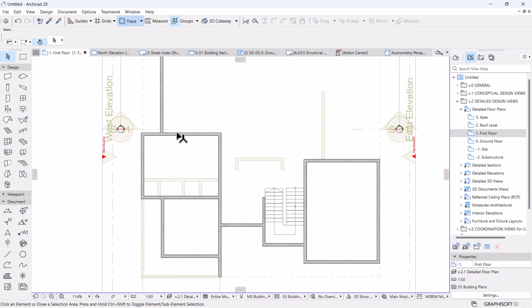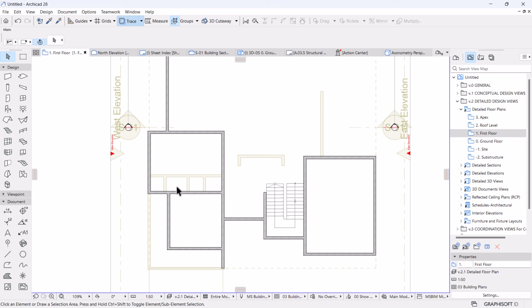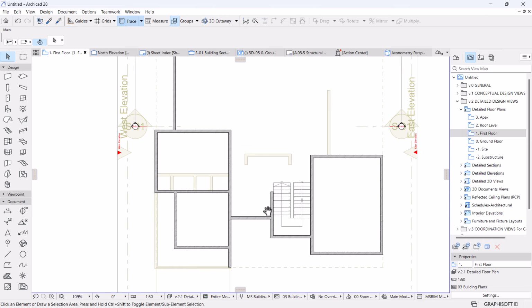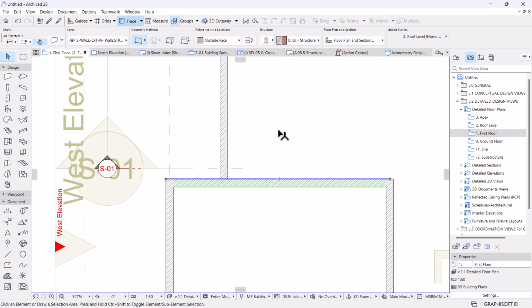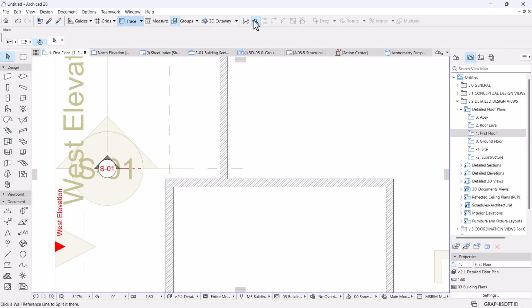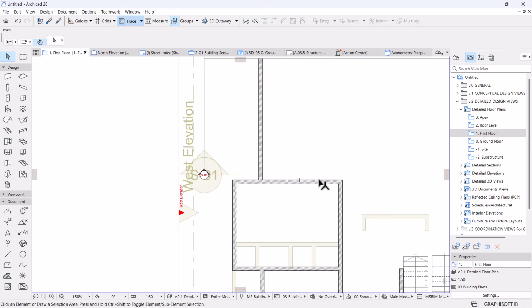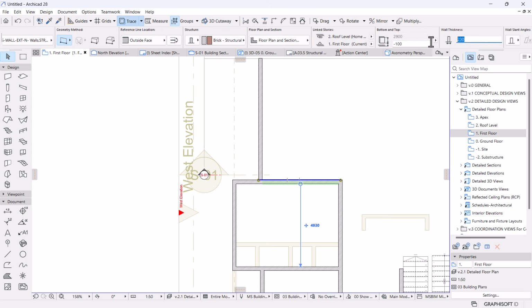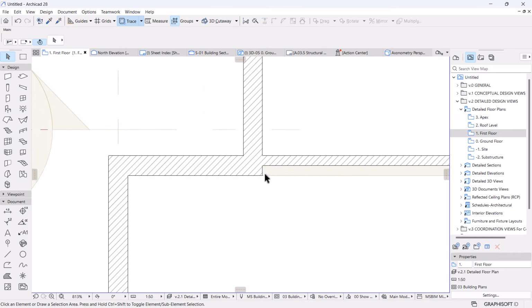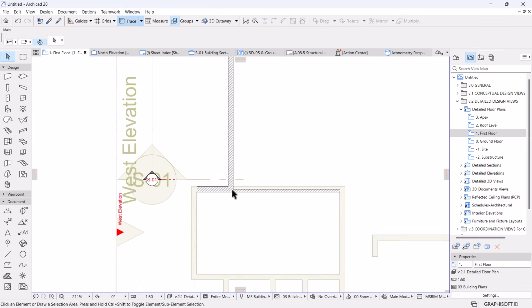Okay, so this wall can be a 115 or an internal wall instead of an exterior load bearing wall. It can be half the thickness, but I'm not that worried because of this demonstration. I'm just showing you the appropriate way, but if you'd want to show that, I'll select this wall, go on the top of your interface and activate the split tool. I'm going to split this there, then intersect to create a clean connection. Then these ones will be half the thickness. The internal wall in this case is going to be like that. Okay, and then I would prefer it to be on this edge, on the corner, so I'm going to turn it out and then Control D, move it right there. Make sure the connections are perfect.